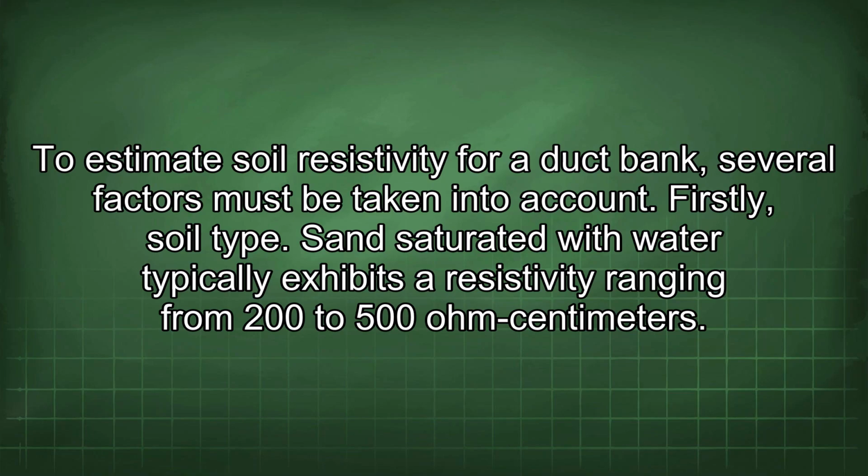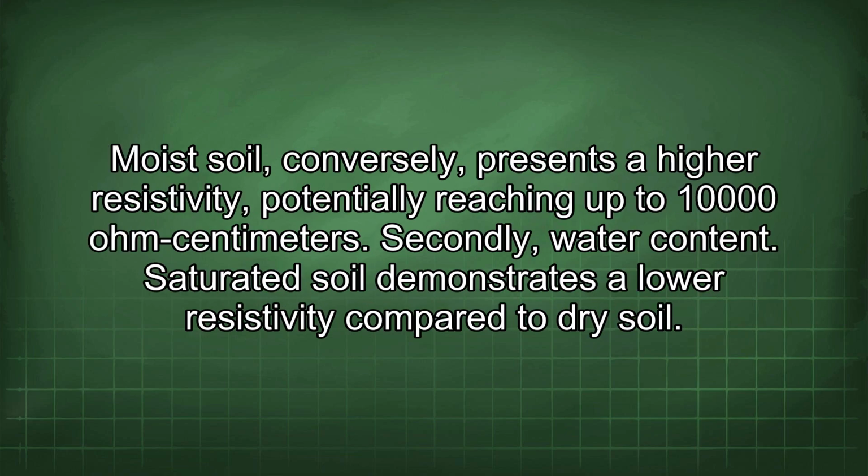To estimate soil resistivity for a duct bank, several factors must be taken into account. Firstly, soil type. Sand saturated with water typically exhibits a resistivity ranging from 200 to 500 Ω·cm. Moist soil, conversely, presents a higher resistivity, potentially reaching up to 10,000 Ω·cm.